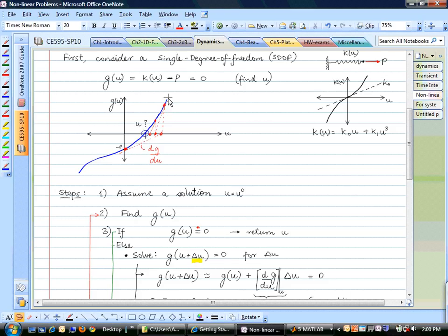If your gradient is even a little bit off, if this tangent stiffness matrix is even a little bit off, you immediately lose your second order convergence. So it will take a lot more iterations to converge to the exact solution. But if it is a Newton-Raphson method with a consistent tangent, then your solution generally converges within 5 or 6 iterations.